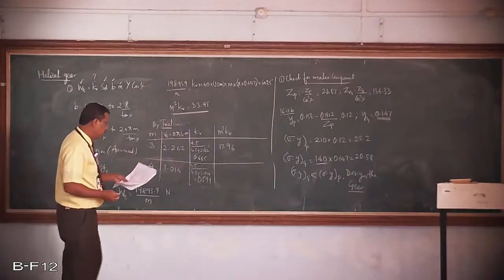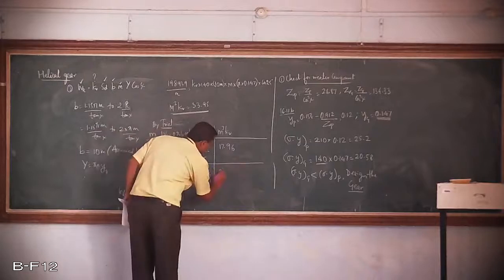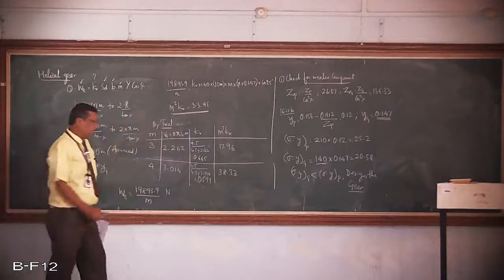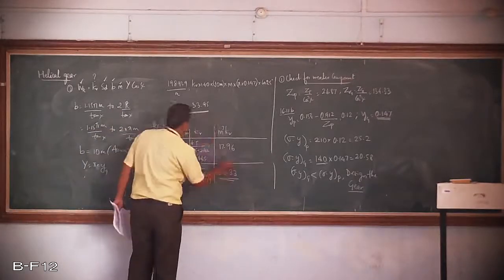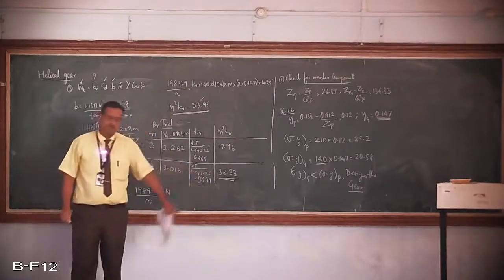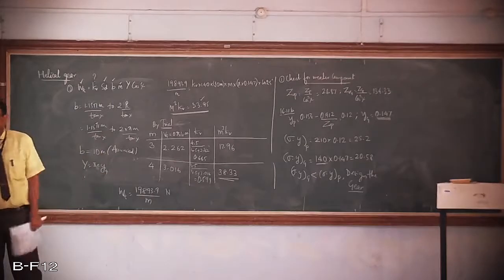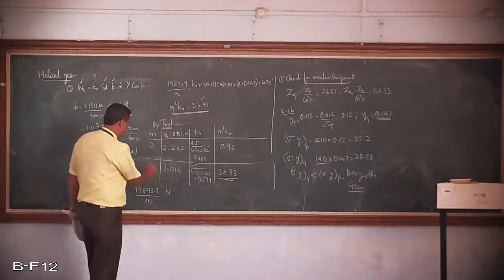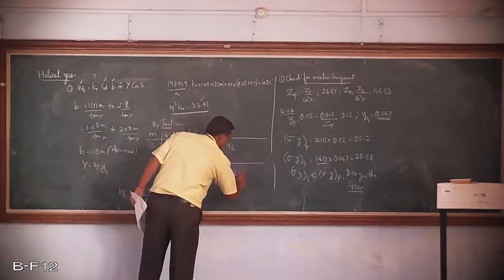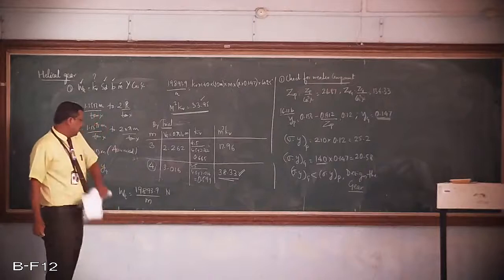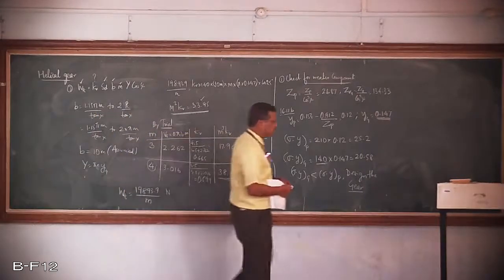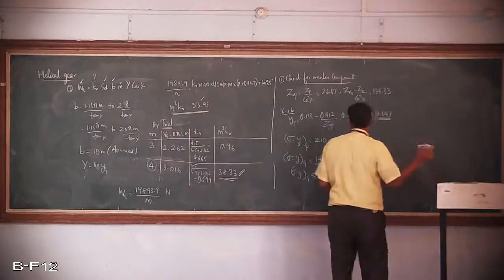Therefore, m cube kV is 38.33. If you check this value, 38.33, we require 33.95. However, with the module of 4, we are getting m cube kV as 38.33, which satisfies our condition. Therefore, we'll go ahead with a module of 4 millimeters. It's satisfying the given equation for m equal to 4 millimeters, so fix the dimensions of the gear.